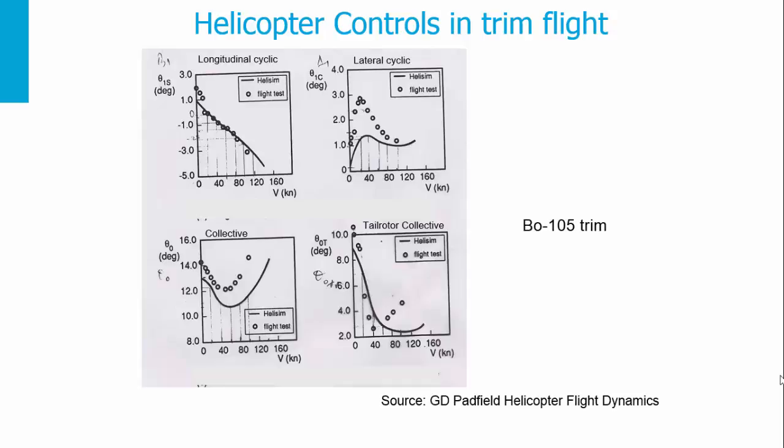For the longitudinal cyclic pitch, actually, if we are increasing the velocity, we need more longitudinal cyclic. So we need to move the stick forward and increase the collective and go nose down with the helicopter. You see also the lateral cyclic.